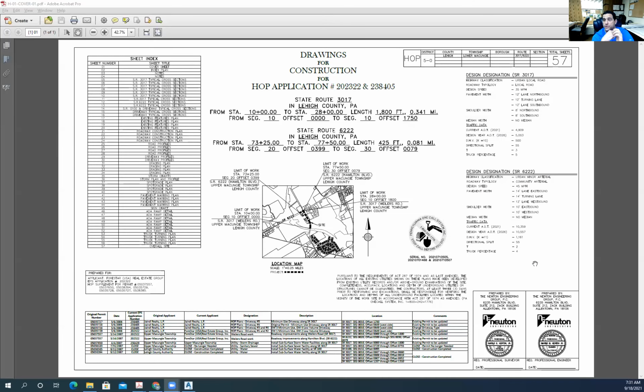For example, Pennsylvania Department of Transportation, PennDOT, their cover sheet is prescribed, meaning you don't have flexibility in what you show. That is the way the sheet looks. It varies from job to job based on the information, like how big the plan set is, the number of sheets and all that. But this whole border and this lower right corner is prescribed. That's all set, that you're allowed to have certain things and you're only allowed to have that. Okay. So there's one example.